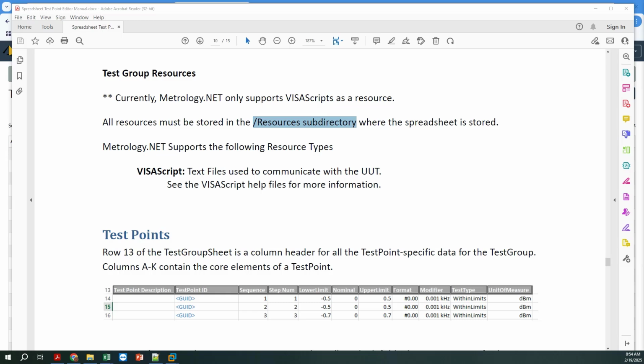Right. Another issue that I run into is measuring AC voltage and AC current using the 8508, being able to set the filter to 10 hertz and below, and also being able to set the DC coupled. And I haven't really figured out how to get it to do that other than modifying the source code for the driver.